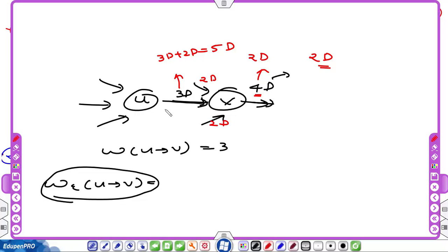I have performed retiming at this point, and by some means I got to know that two delay elements should be removed from the outgoing edge. So a similar amount of delay element should be added to all the incoming edges.